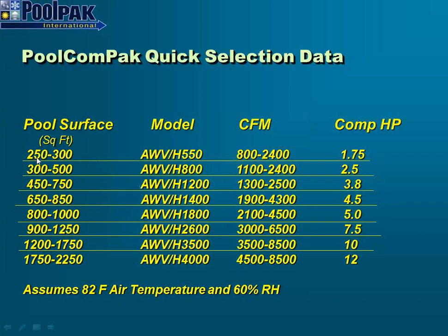PoolPak can handle anywhere from 250 square foot pools up to 2,250 square foot pools. There's some judgment required in its application. The ratio between the pool area and the pool natatorium volume can result in using a larger or smaller unit as required.